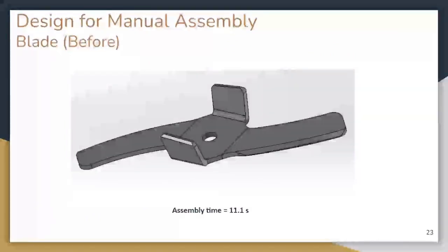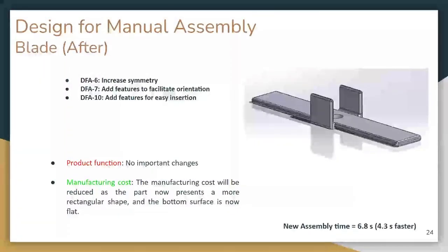This is the design of the blade before the redesign, and it had an assembly time of 11.1 seconds. After the redesign, we were able to increase the symmetry of the blade at the same time that we're adding features to facilitate orientation and features also for easy insertion.